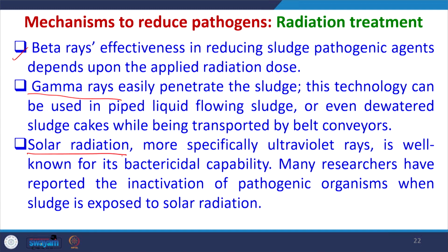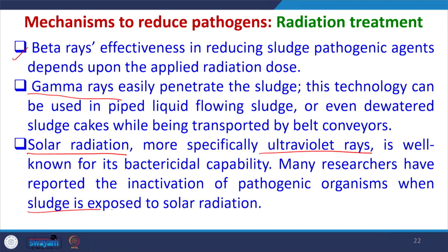Then solar radiation, more specifically the ultraviolet rays, if they are available, generally they will be very less, is well known for its bactericidal capability. Many researchers have reported the inactivation of pathogenic organisms when sludge is exposed to solar radiation when the amount of ultraviolet rays is higher, but it is dependent, because the ozone layer blocks fortunately most of the ultraviolet rays. The ultraviolet rays which are available at ground level are generally less. So, the treatment by this method may vary.